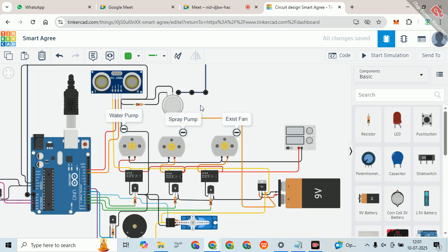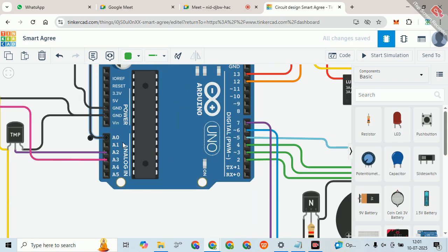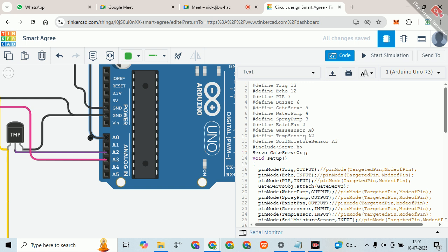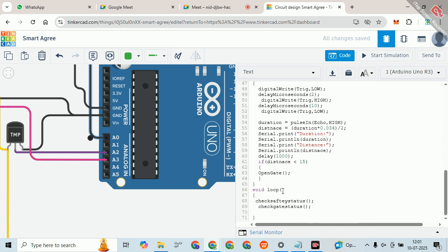As you can see here, the smoke sensor is connected to pin number A0. Okay, and for the smoke sensor, we call it the gas sensor. We saved it as a gas sensor. For the gas sensor, already we are using one word, A0, attached to this. So instead of using A0 everywhere, we can use gas sensor as an alias name for that, right? So now I'll go with Serial.print. As you already know, yesterday we printed the sensor value. We are using the serial monitor just to print the sensor value.